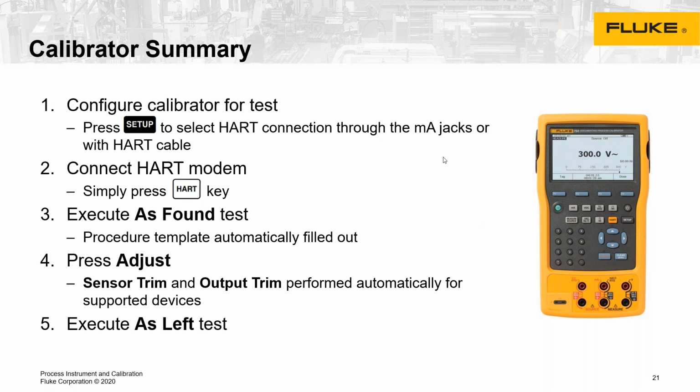we will want to set it up and configure it to connect to the calibrator. So in this case, we're going to do a HART smart temperature calibration. So we would configure the device to look for the HART signal across the milliamp jacks.